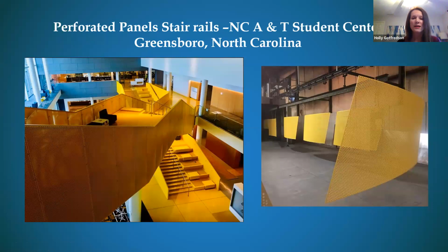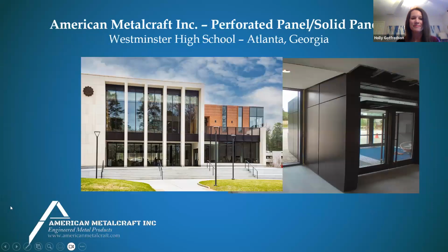We are always looking at deflection standards and making sure we can get the most flat panel possible. But our recommendation was not taken, and so they wanted the thinner gauge, so you can see a little bit of a wave there. But that's why, when you have those conversations with your panel manufacturers, definitely listen to the recommendations to achieve the best look possible for your project.